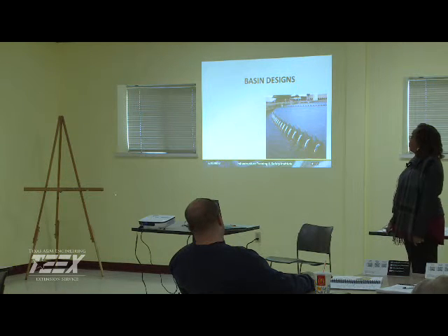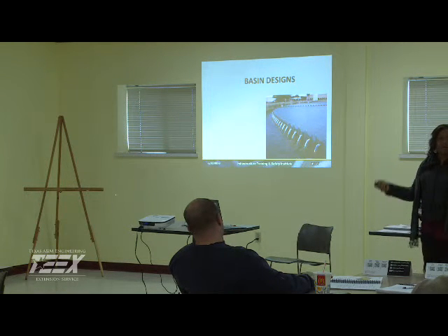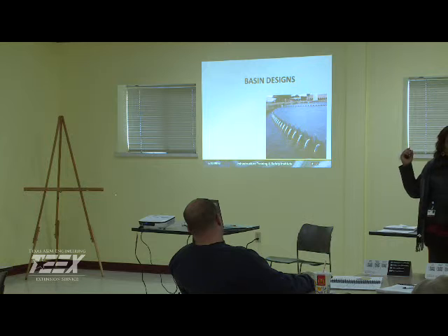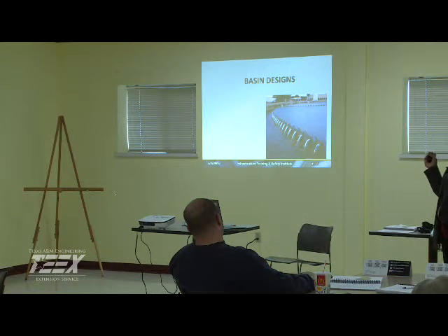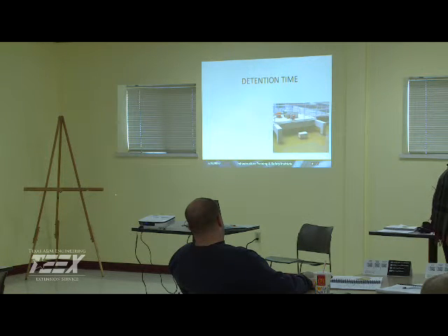Again, you can have different basin designs. We saw rectangular basins, which are very typical for water plants. We also have circular basins: center fed with the circular one, circular peripheral fed, or square center fed.